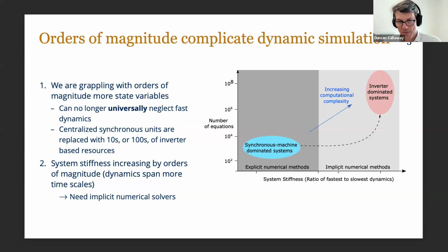And if you're not familiar with numerical integration tools or haven't studied them for a while, the big difference that happens when we go to implicit numerical methods is that essentially each time step requires at least one root finding effort. That is, there's some iteration that happens within a time step to find the roots to a system of equations. And so implicit numerical methods tend to be slower for obvious reasons, but they're required when you have a very stiff system.